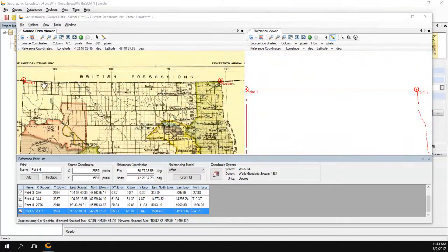By comparing my two locations, I know that my curve in my image is not going to match with my geospatial data. I could compare it to the northern curve as well. Our source image here is curved and our reference data is straight. So this linear affine transformation is not going to appropriately line up this boundary with this straight line in our geographic coordinate system.